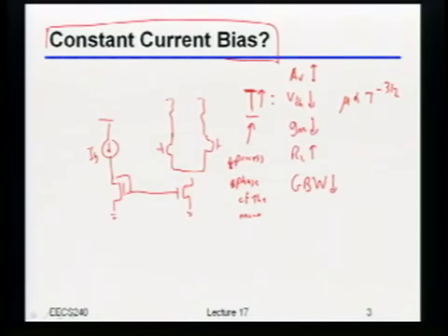The real trick with all these biasing and reference circuits is to figure out what the thing is that you actually want to be constant. Once you know what that is, there's another key step: look at the physical units of that thing you want to be constant.